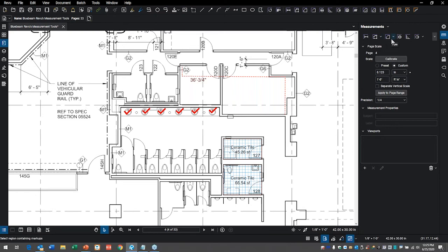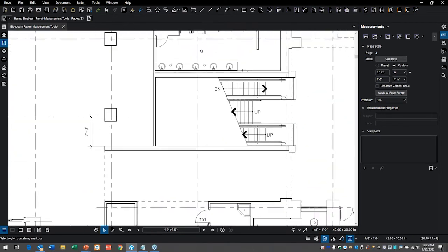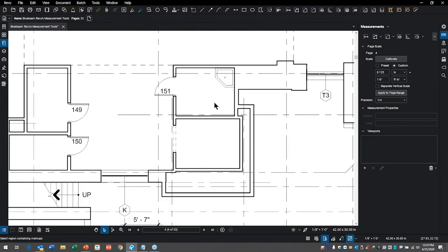The area is probably the one that would be used the most if you're doing those kinds of two-dimensional takeoffs in plan. The other thing you can do with areas is you can give a wall height so that you can not only get an area, but you can also get the heights of the walls in that particular room. The area tool in the toolbar over here in the panel, you have, I'm in the cutouts. I don't want to do polygonal cutout. I want to do areas.